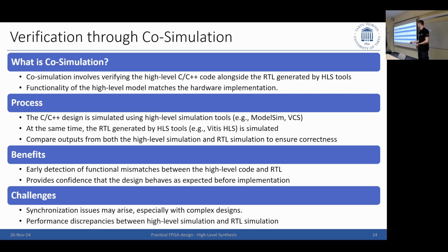Of course, there might also be discrepancies between your high-level simulation and your RTL simulation. It is the further down you go in your process. We had this also in VHDL: the synthesis simulation or resource reports are not going to be the same as the implementation ones, because you have implemented your design in much more detail after place and route. So that applies, of course, here too. So you need to still go through the rest of the design process to be sure that it works.